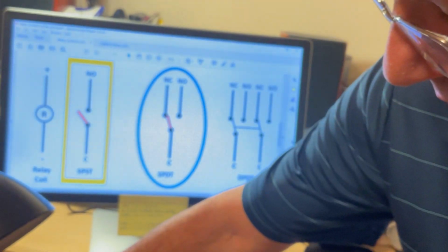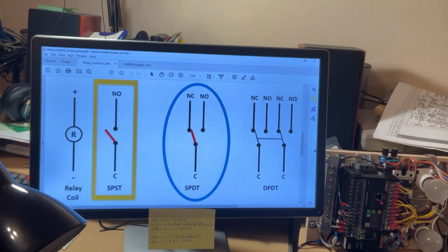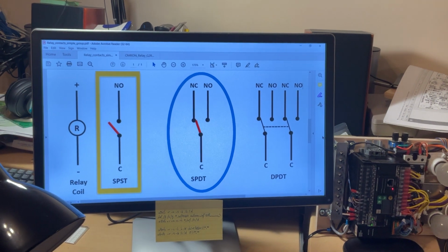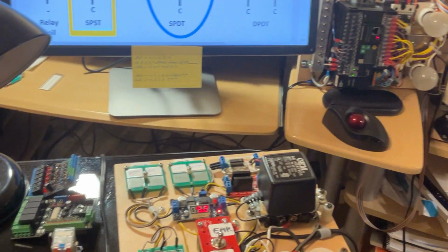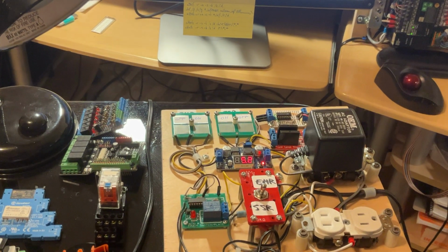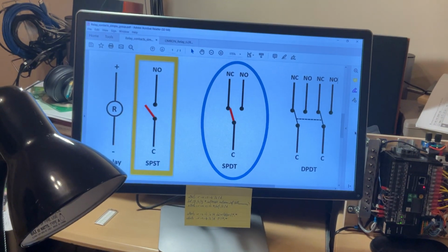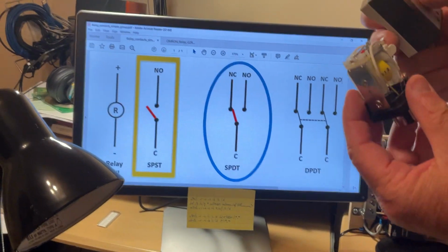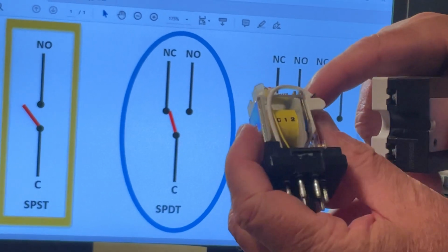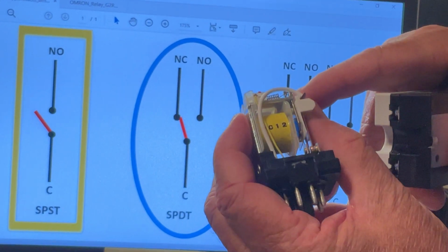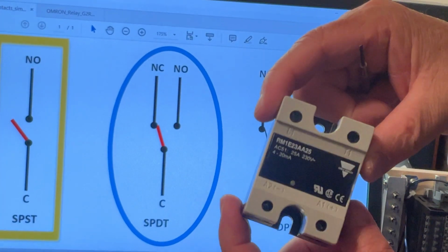So far, so good. Now I'm going to use for the relays 2 kinds of classifications. There are a lot of classifications for the relays because there are so many. But for the purpose of using the PCB relays, I have 2 kinds of classifications. The first one is to make a distinction between the traditional electromagnetic relay, obviously, as we discussed before, and you can see it has moving parts, and the solid-state relay, having no moving parts. This one contains TRIACs.